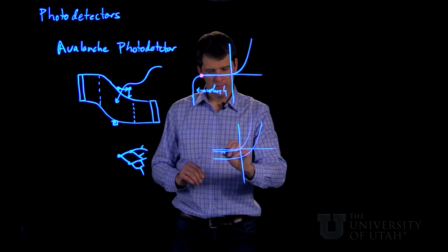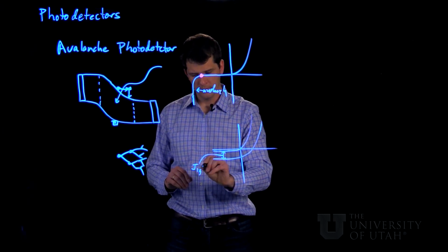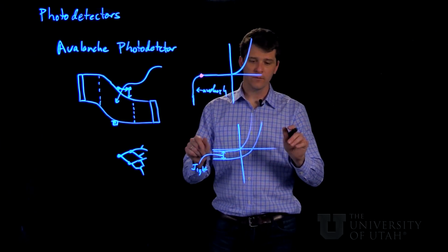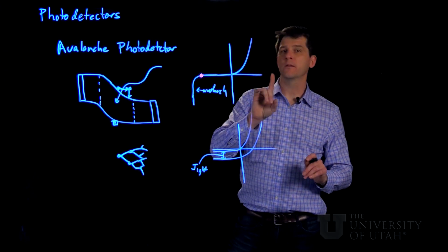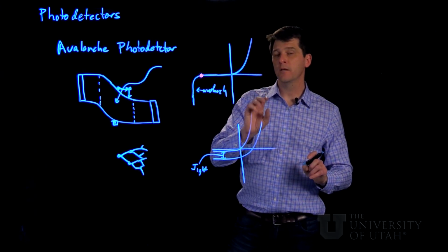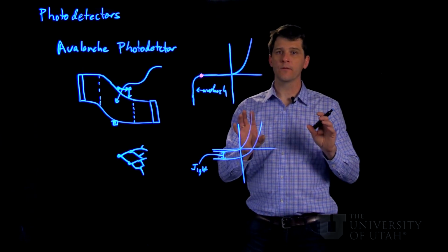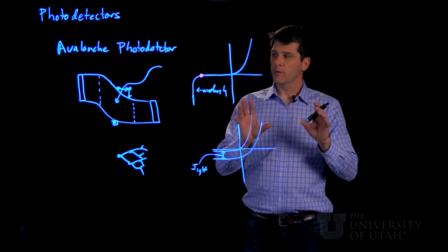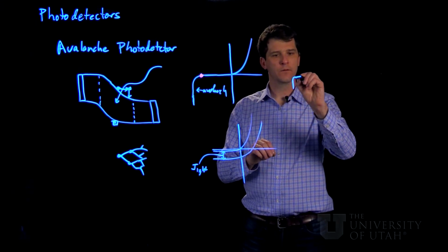This J light was linearly proportional to the photon flux. So one photon generated one electron-hole pair, and thus the maximum light current for those devices, even if they had 100% collection efficiency, would be exactly equal to the photon flux.